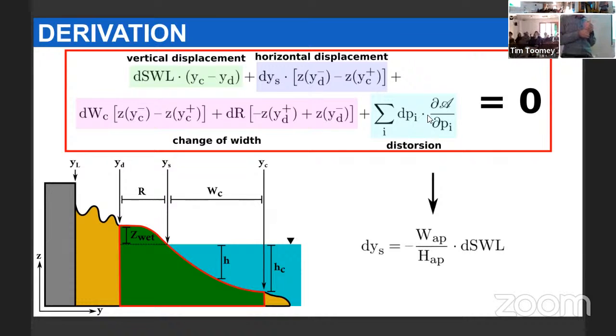Well, I don't think it's that complex anyways. Yes. Because I would say that normally the sediment you have in the dry beach is coarser than the other one. So if you are assuming that the volume from there is going to the rest, over the long time that is going to change slightly your distribution of sediments towards a slightly coarser sediment. So that would give you a steeper profile on average in the long term.